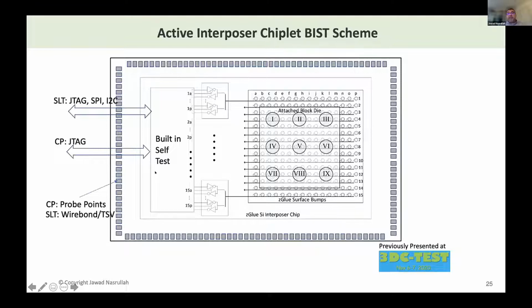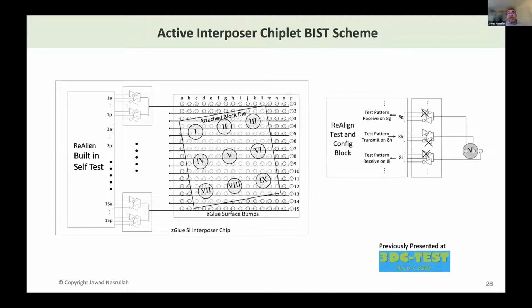The built-in self-test can communicate with the external hardware via JTAG when it goes to testers, but when it goes to more like system level tests or final tests, we had exposed JTAG, SPI, I2C, and some of these other things were super helpful in running system functionality, especially when you start thinking about loading firmware and stuff.